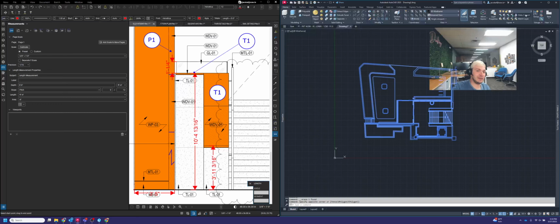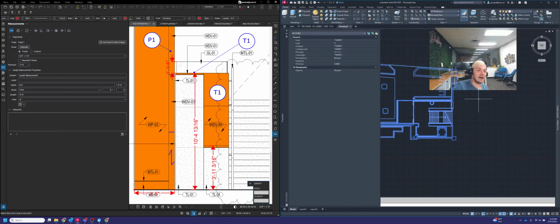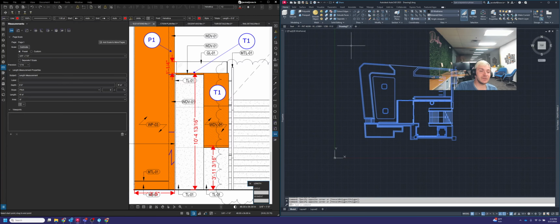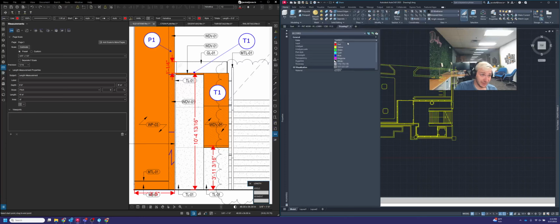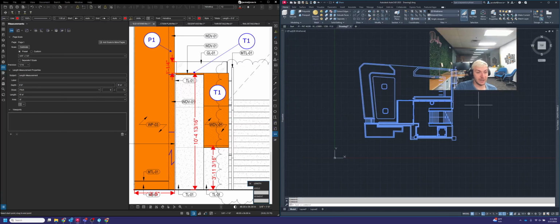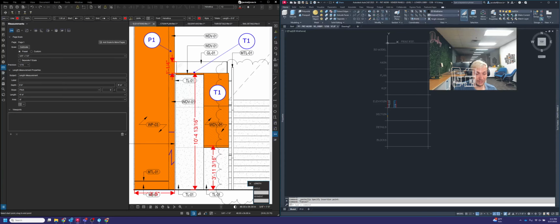If I was to bring that into my CAD drawing for P1, it's going to bring in all of these extra layers that I don't want. It's just going to clutter my drawing and slow things down. One other thing that I like to do is, once I've highlighted this and put everything on layer 0, I go into properties and change all of these to ByLayer as well, instead of Varies or anything like that. Okay, so I'm going to copy this out of here now and paste it into our current